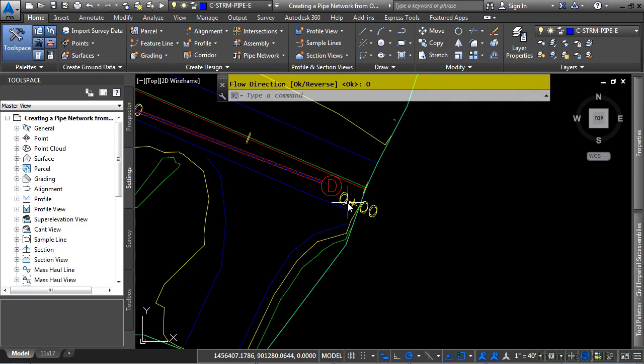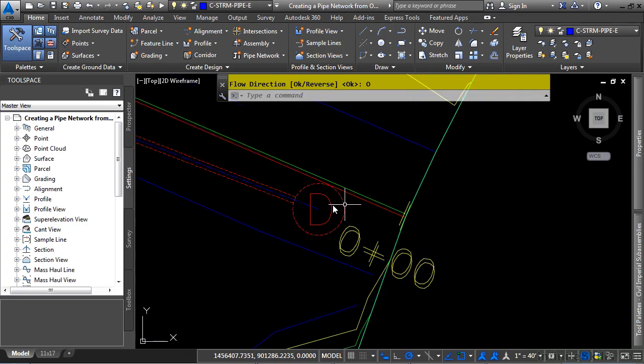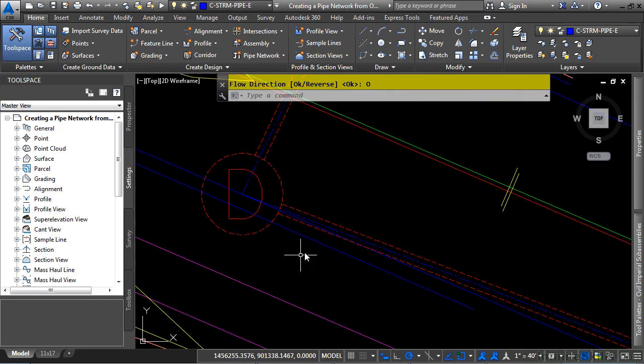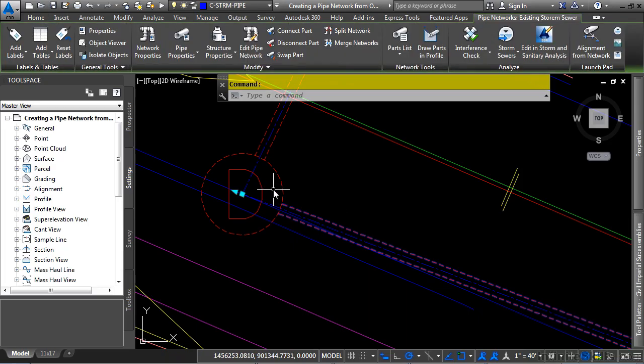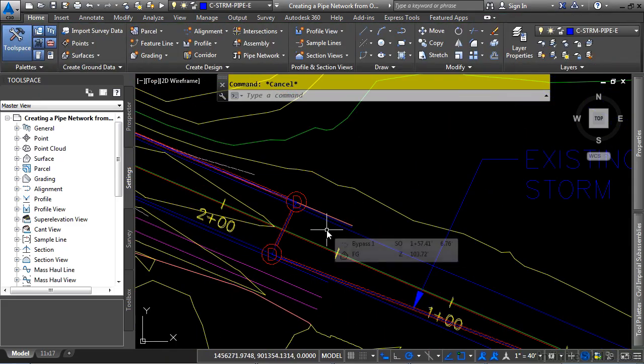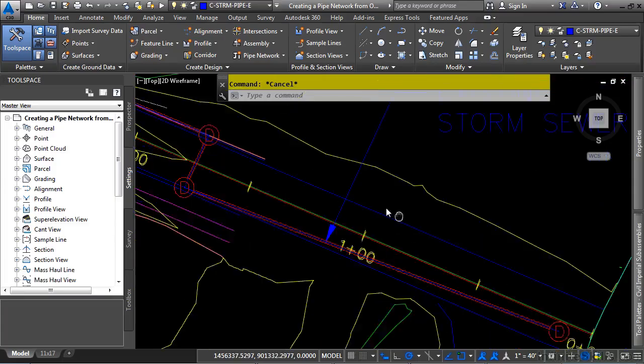And here is our network. As you can see, we have the drainage manholes set here, and the invert elevations are there as well. To quickly verify some of the elevations to make sure that they're there, you can simply select an object and hover over the grip, and notice in the drawn coordinates, it'll actually update with the X, Y, and Z. If you'd like to see this in a profile, let's go ahead and do that real quickly.